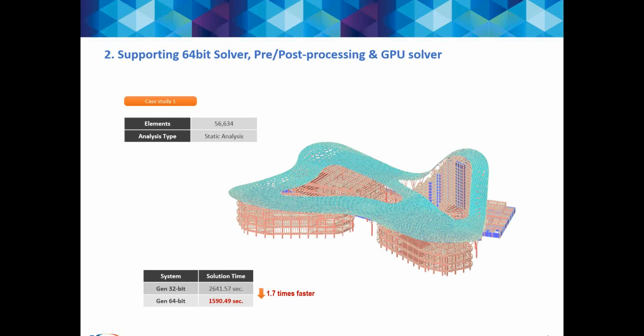In order to use the GPU solver, a high-performance graphics card is required, and the GPU has been applied in the multi-frontal solver of Midas Gen in order to accelerate the calculation of simultaneous equations, which is the highest portion in FEM analysis, like the solid elements.